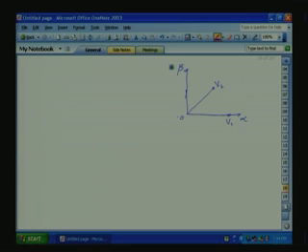Now this is our Vs, the sampled voltage space vector, which is tracing a circle. For a particular sampling period, let us say Vs makes angle alpha with respect to the start of the sector, V1. In sector 1, V1 is equal to 100. Now, let us find out the volt second along the alpha axis.